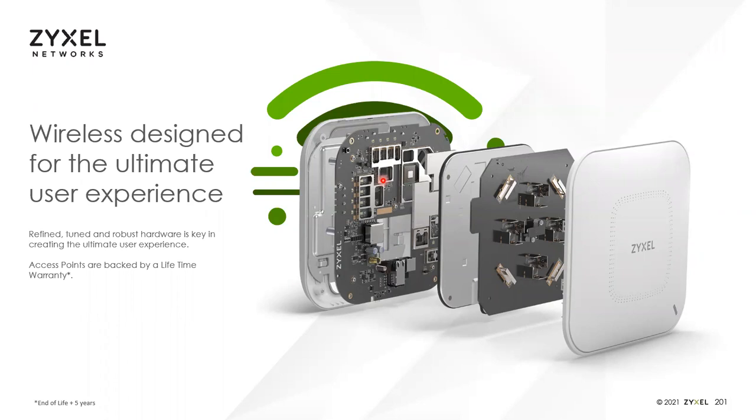And then the next thing you will notice is there is generally going to be another plate of metal above the PCBA, and then we will have another board with our antennas mounted to that board. Most of our competition, including a lot of our more expensive competition, is mounting their antennas directly onto the PCBA. So by separating them from the PCBA, you get a better signal to noise ratio, and this metal shield sort of acts as a reflector to sort of boost the signal that the antennas are picking up.